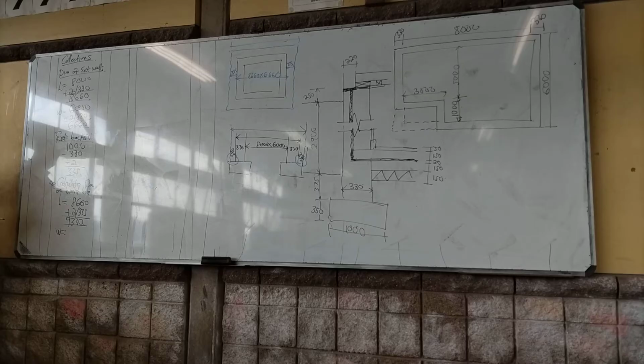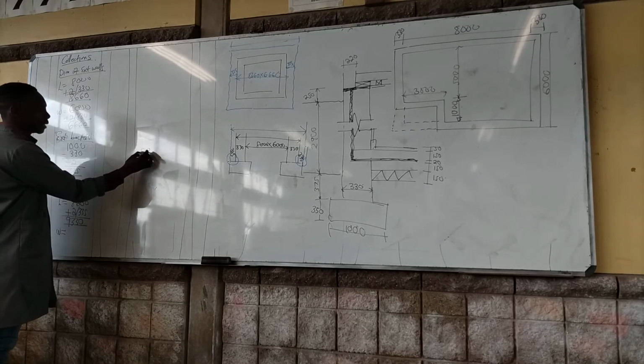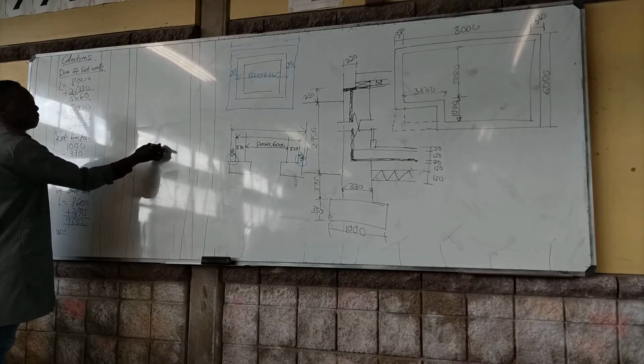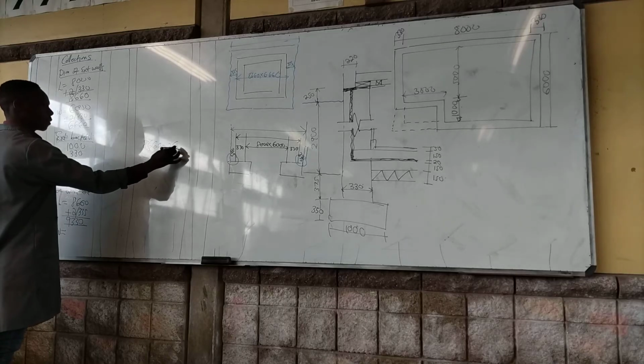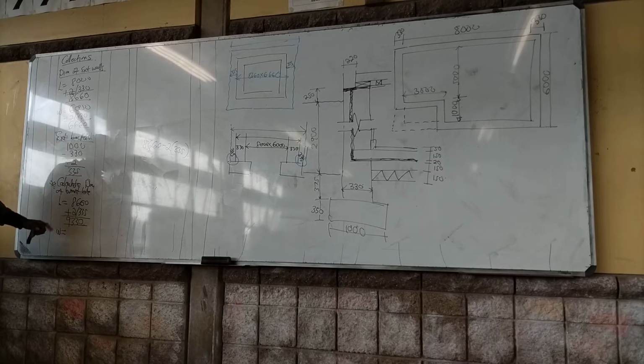The length of the basement hole is wrong. It's not 9330. No, it's 9270. Is it? Please, let's confirm. If I'm doing that, see 8,600 plus 2 times 335. Make sure you don't confuse your calculator. Your calculator is going to give you whatever you tell it. So it's going to be 8,600, make sure you put the brackets, plus 2 by 335. It is correct.